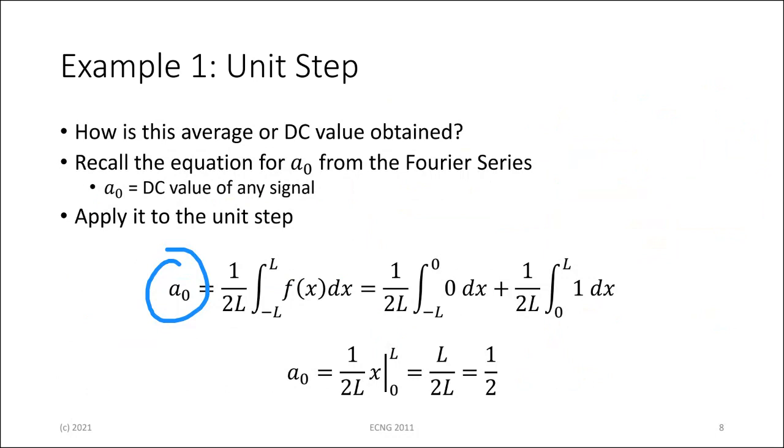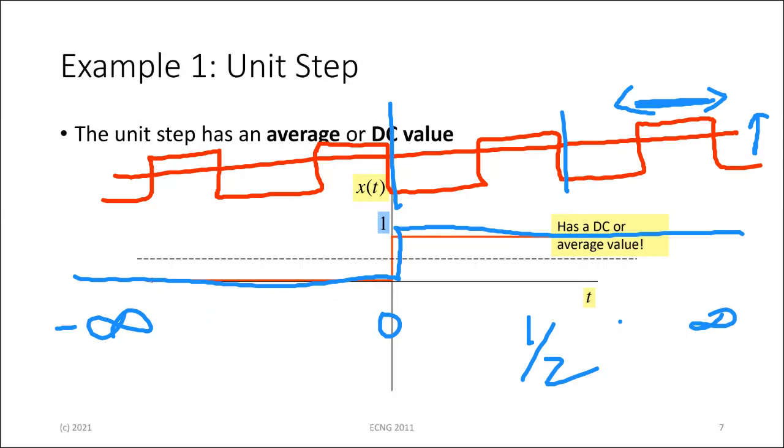The Fourier series of something, you would have learned this already, I think, in 2013. This was on the extra slides that I told you about yesterday, how to find the Fourier series, the trigonometric form, if the period was not minus and plus pi. But you don't really need to know that. You could understand it straight from here, just by understanding what we did originally with the pulse. If I stretch the pulse out again, half the time it's 0, half the time it's 1, so the DC or average value is going to be a half.